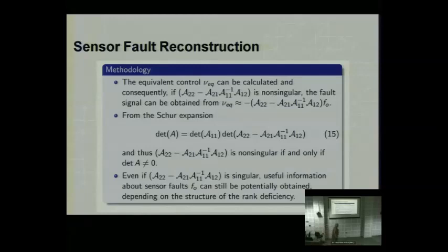You have an observer. You have an inverted pendulum. You can look at some of these ideas in your Simulink model. You can put in a sensor fault. All it means is in the Y, you just have to add something to it. You can push it through the observer, and you can look and see what you can do here with estimating the sensor fault. So you can see what happens. I'll give you some hints of the sort of things you see.